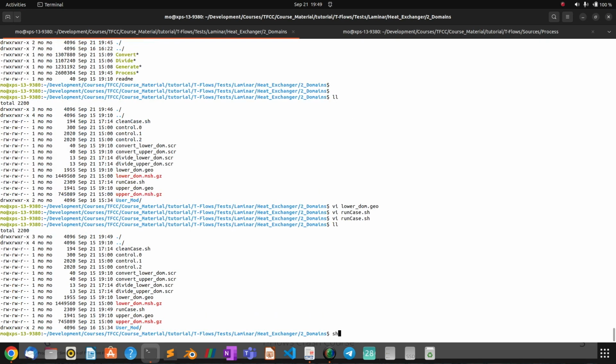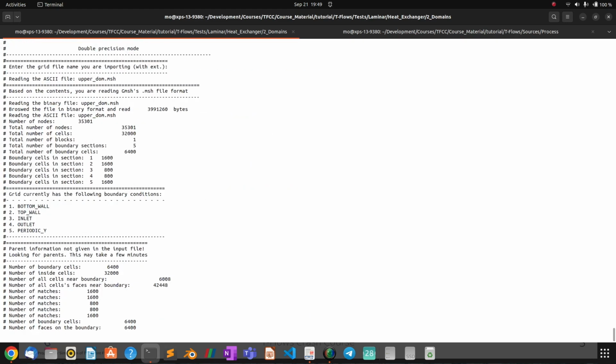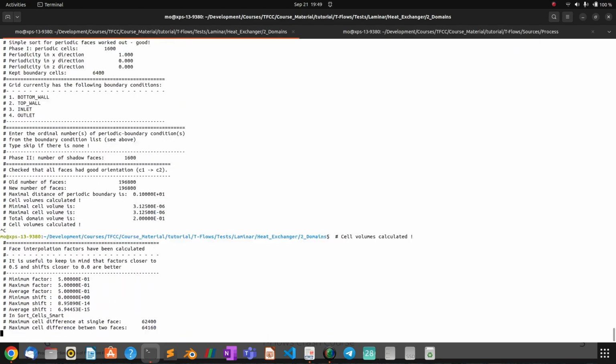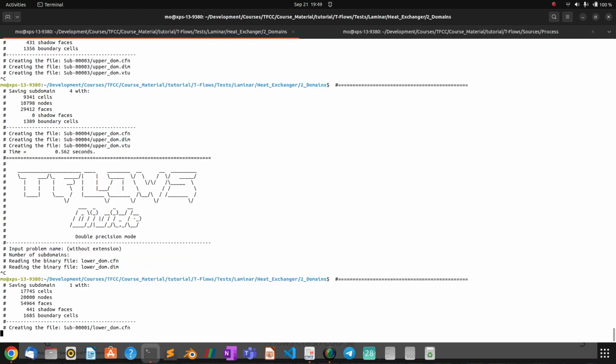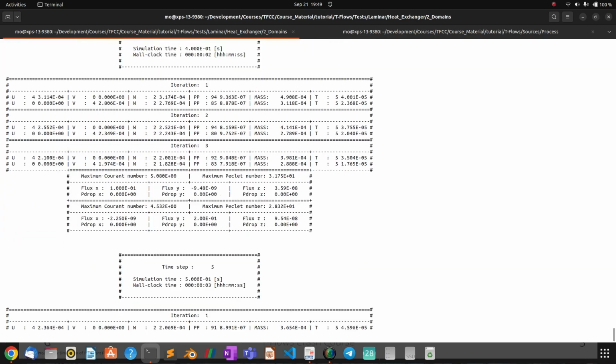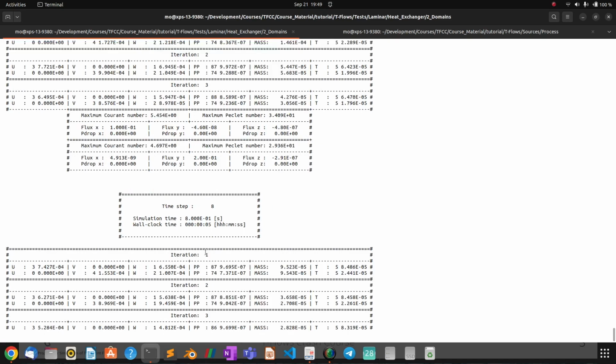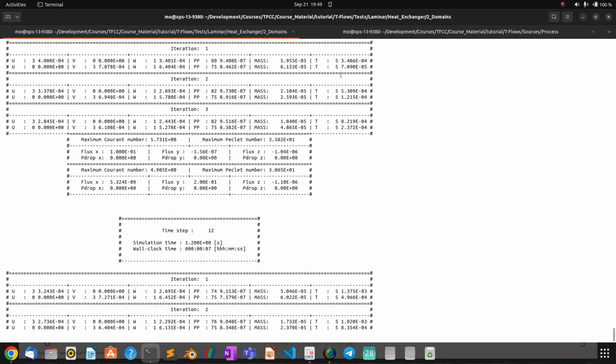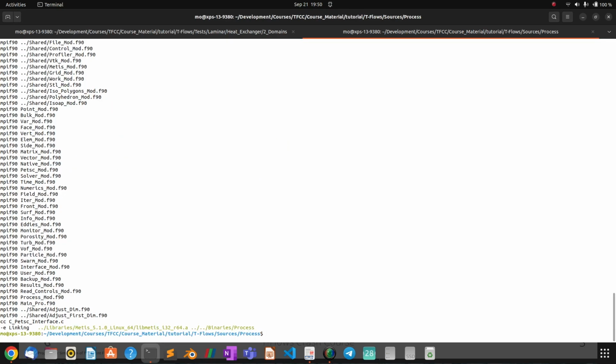So let's go ahead and sh, and then we say run the case in parallel mode. So we pass the word parallel as a keyword, parallel or serial in the same command, and then we put this ampersand sign just to protect our output. As you'll see now, if you type Control C on the keyboard, it doesn't matter so much, or it doesn't bother by your input, because it's protected in the background. All of these scripts are being run in the background. It's not interrupted by your input now.